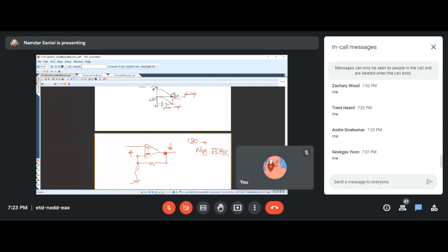Okay? Now, if we had something here that would introduce an additional 180 degrees, then our output phase, whatever it was, would be the same on the input side. That would cause a positive feedback.